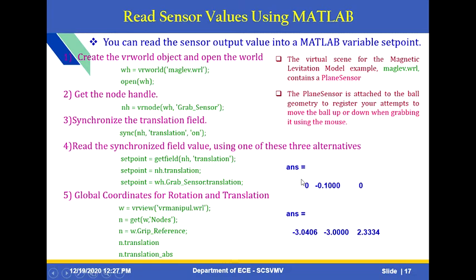After hitting the run button, you will get this answer: the sensor readings value. Here is another way. For the previous one, you have to get the VR world using the vredit command. Then after hitting the vredit command in the command window, you will get this VR editor block where you have to choose a new design and add nodes like materials. What are the materials? What are the textures? What are the objects you can add, and set the viewpoint also. Here another example is by using the MATLAB main window or command window.